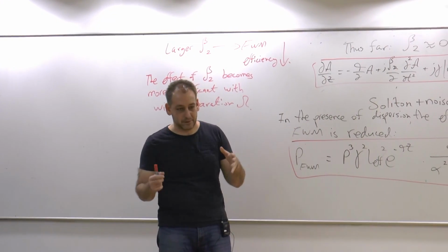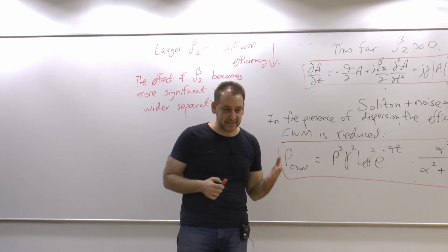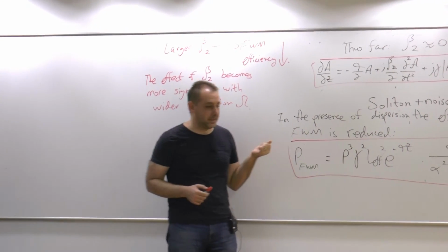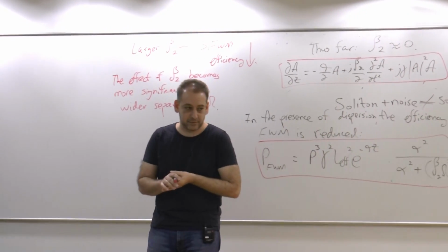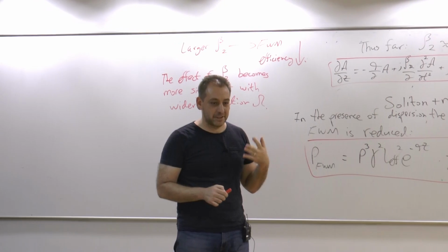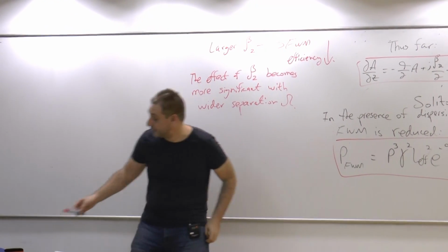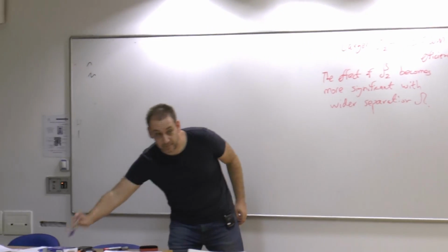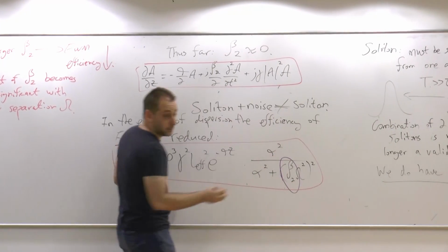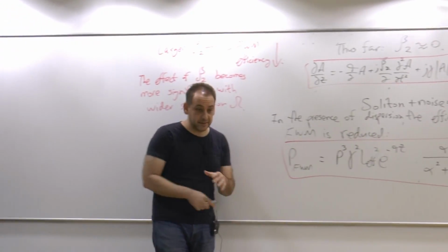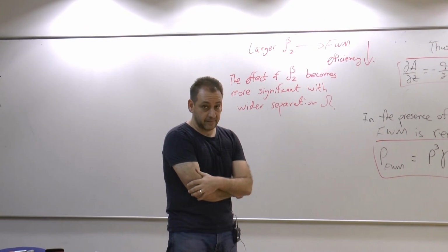It is coupling power, coupling signals from one omega to another omega, and this is a disaster. So any way to mitigate this effect, any way to reduce this effect is a fortunate break if you try to do communication. And this is why optical fibers, at least the best of them, deliberately maintain beta 2 that is not zero, because it greatly reduces the extent of four-wave mixing due to nonlinear index.